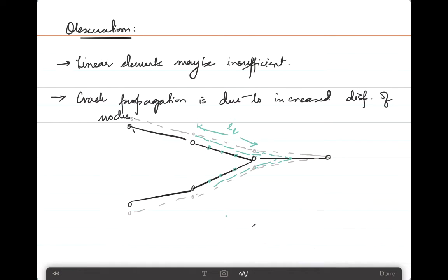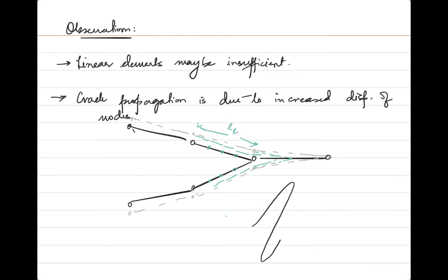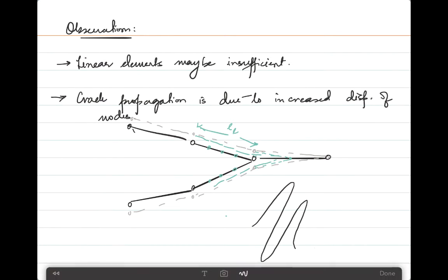This also means that the local softening behavior that we saw in terms of oscillations will be much higher, causing a higher size of oscillations with higher elastic deformation for energy dissipation. And therefore, a decrease in the slope of the traction separation curve will also occur. So, all in all, the moral of the story is that higher order elements may work better, but a combination